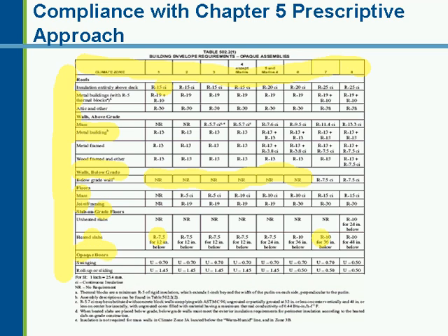And with opaque doors, you will find you can put as many opaque doors in your building as you want to. It doesn't count toward your glass total. But in some categories, they are going to have to be fairly efficient, typically in colder climate zones. For swinging doors, for example, the U-factor requirement will be 0.7, and roll-up doors, like you would find in a service bay and that type of thing, in the colder climates, the U-factor of those will be a 0.50, which will basically indicate some kind of an insulated door.